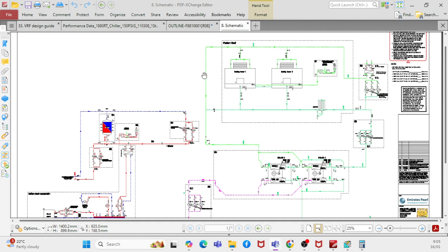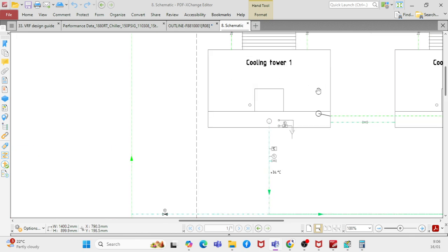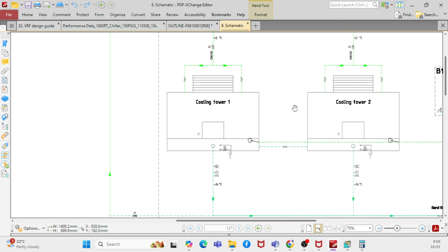The water goes to the cooling tower and there are nozzles on top that spray the water, just like a shower. So your reasoning for calling it an open system is that if the pipework in the cooling tower were closed, you would still call it a closed system. But in the cooling tower, by the time it reaches there, it sprays down, so there is a break. Hence it is an open system.